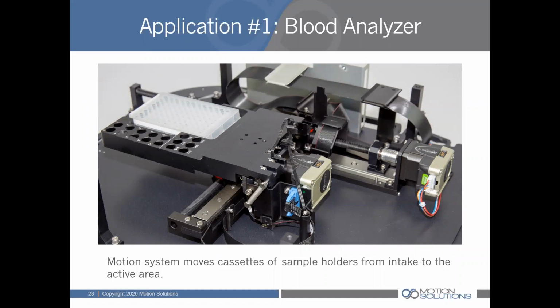And remember, we're talking about the cumulative accuracy of your lead screw, of the X and Y motion system both being straight and perpendicular to each other, and the carriage that's hanging off of the third rail, supporting your well tray, being really flat. Because if that well tray is tilted, that'll take part of your error budget. So it's important in this application that the sample be held very accurately, that the motion be accurate, and that there be very little clearance in the bearings.